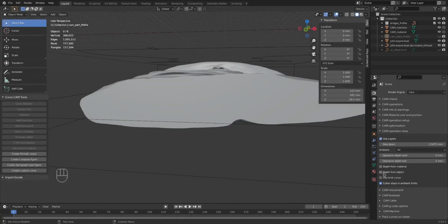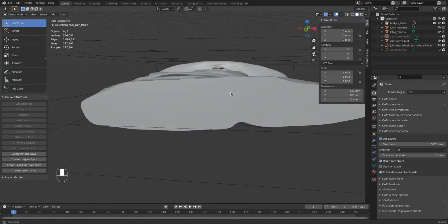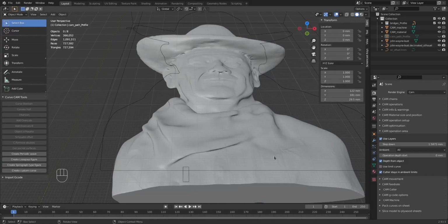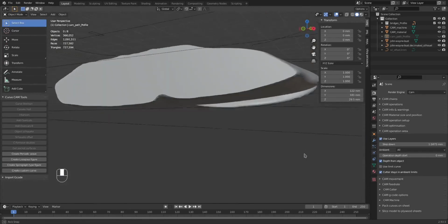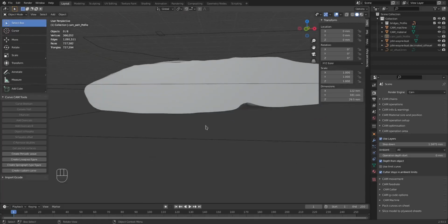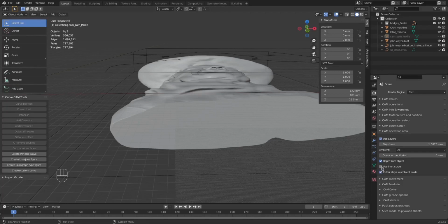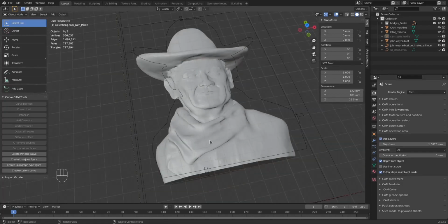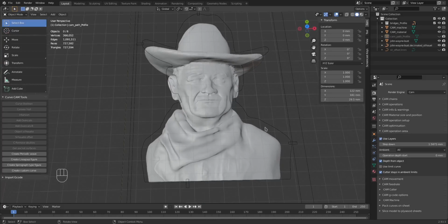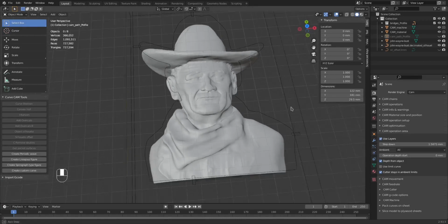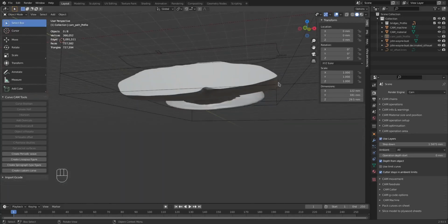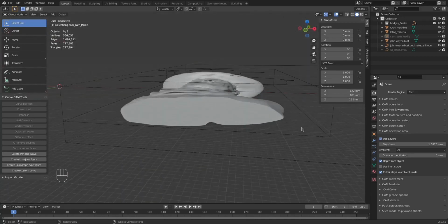We're going to go with depth from the object, and that means it's actually going to use the object as opposed to the material depth, and it's not going to go below the material though. You'll see what I mean when it comes up. And we are going to use a limit curve because otherwise this parallel operation will cut across the entire material, and it would be cutting all this down to the material thickness all the way down. But we don't really need that because we're going to be cutting this out, right?